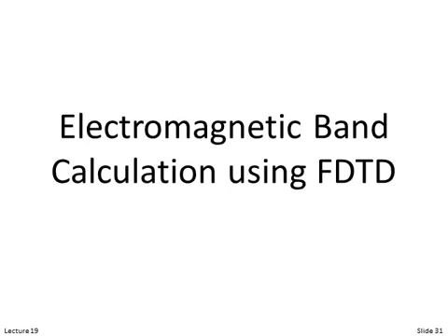Okay, so on to our last topic. We will restrict our conversations to calculating band diagrams, but I do get the question a lot: can I use finite difference time domain to calculate modes in a waveguide? In fact, yes, and it's really this exact same procedure. We just don't need the periodic boundary conditions at the edges. We certainly can use periodic, but we can use about anything else. But it's done the exact same way.